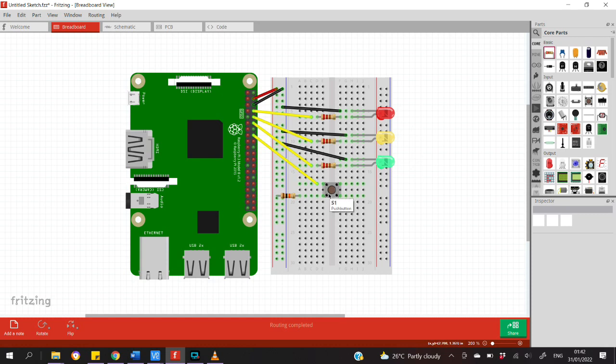And as we can see, the push button has a pull down resistor with a value of 10 kilo ohms, and every LED has a 220 ohm resistor, which is not indicated in the materials but is important for the circuitry to work with our intended application.